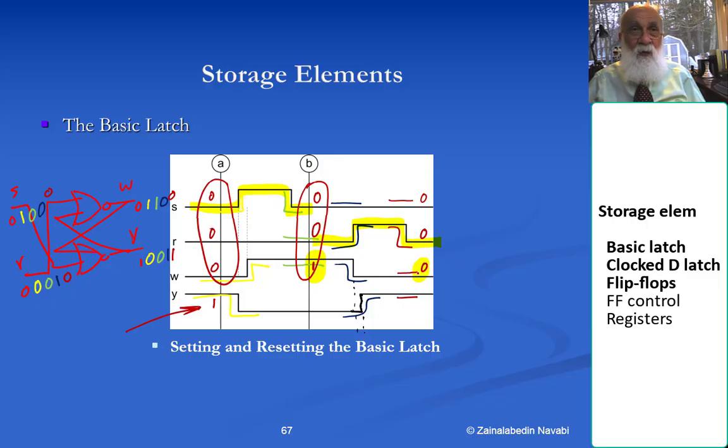And therefore, I'm calling this an SR latch. S sets my output to a 1. R resets my output to a 0. Okay? My circuit remembers whether the last pulse was on S or it was on R. And that's all my circuit remembers. My circuit doesn't like to see simultaneous S and R values of 1, and therefore I will always avoid that. Alright, so this is a good thing.